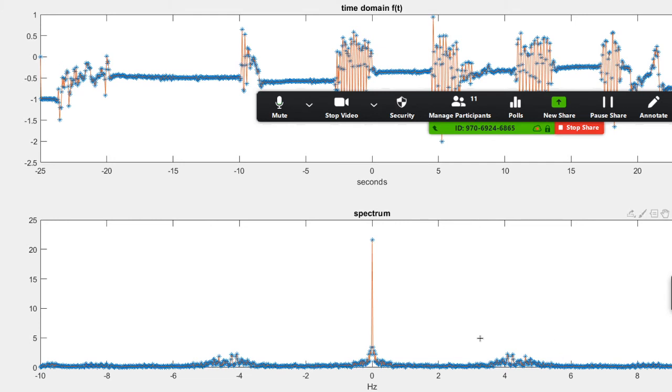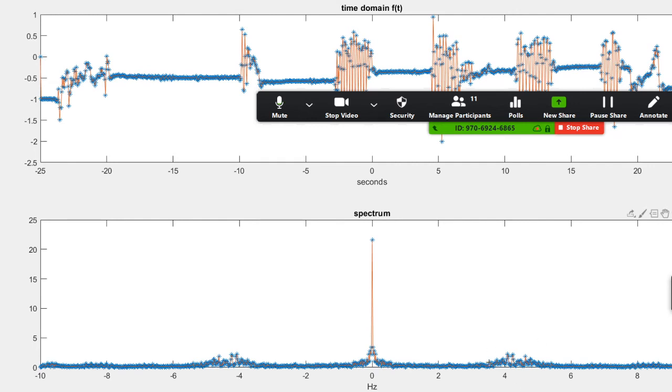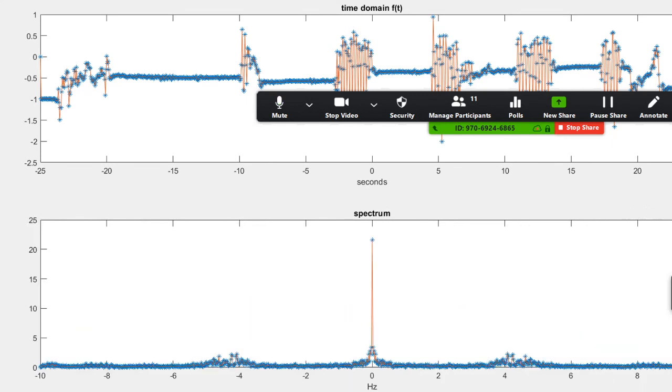You generate the first one, then you filter to get rid of the DC component, draw the spectrum and show your major spectrum, and then do a low pass filter to cut out the noise. Maybe here is noise. It's not your generated signal. It's some noise, so you can low pass this part.